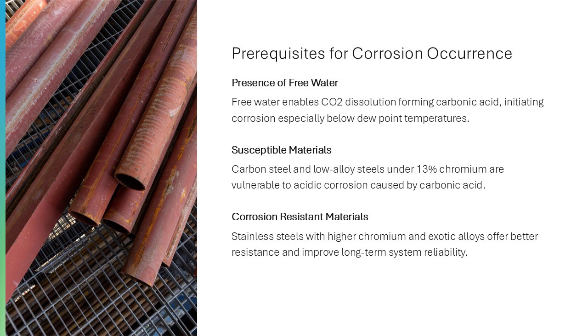Free water acts as the medium for CO2 dissolution, forming carbonic acid that initiates corrosion. This water may enter the system as liquid or form as condensate when operating temperatures fall below the dew point of the fluid mixture. The location and amount of free water significantly influence where corrosion develops. The second condition involves material selection.